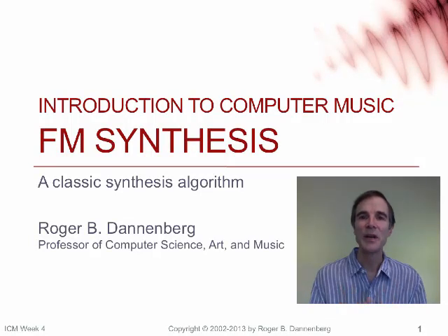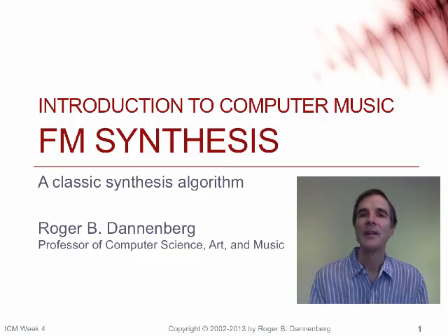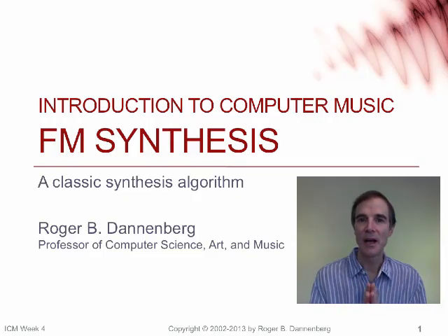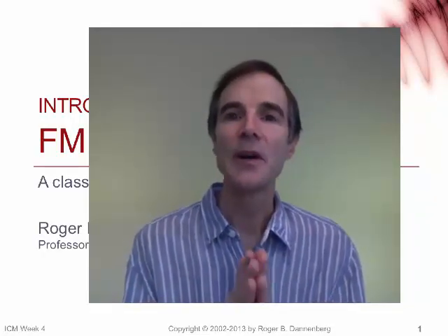We're going to go in a new direction now of FM synthesis or frequency modulation. This discussion is going to parallel our discussion of amplitude modulation, where, if you remember, first of all, we talked about multiplying a signal by an envelope, which is kind of a slowly moving shaping function. Then we talked about multiplying by a more rapidly fluctuating signal to form amplitude vibrato. And then finally, we talked about multiplication by audio rate signals, doing amplitude modulation, where there we started with sinusoid,